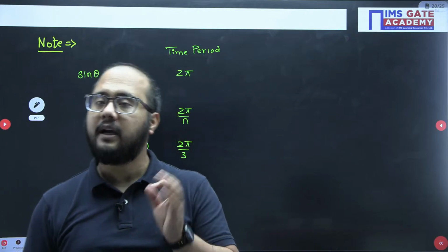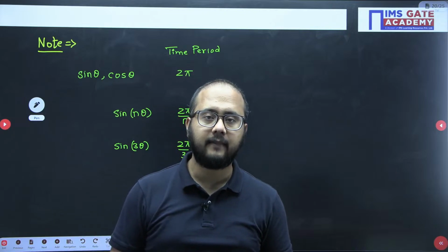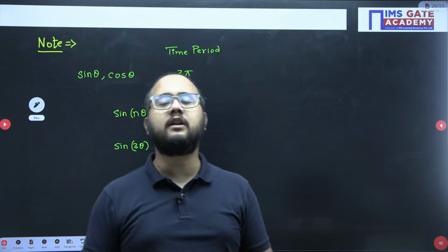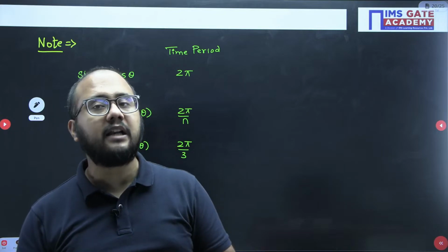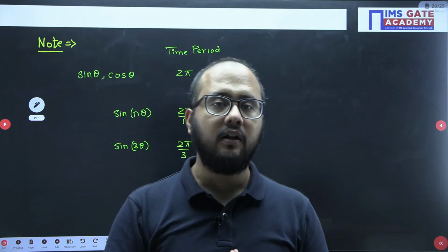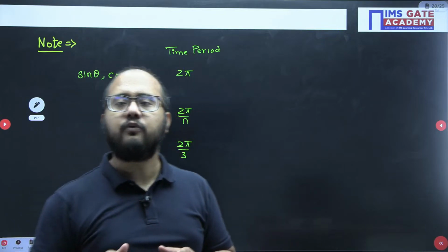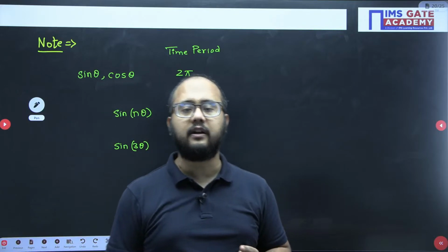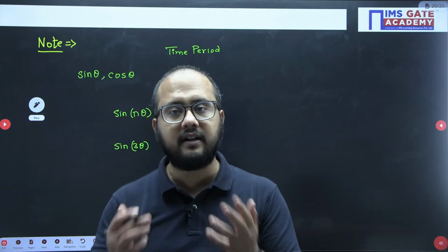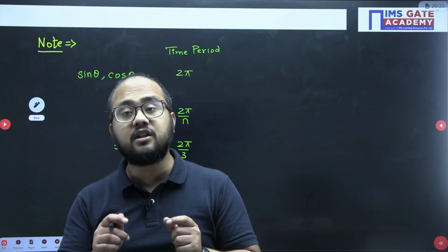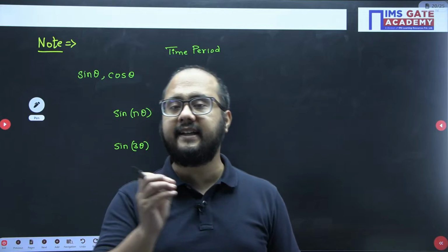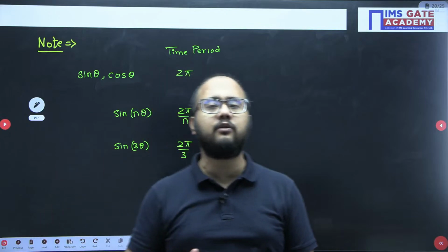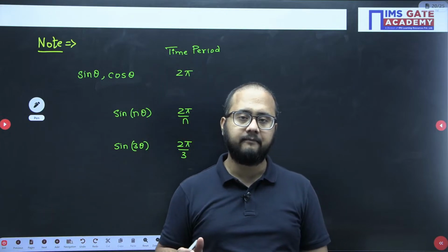Mean torque multiplied by omega average. So calculation of mean torque is very important, and for that, the work done per cycle is required. And as I already told you, work done per cycle calculation requires two relations. Either we can use the area under the T theta diagram, or the integration of the torque expression, T d theta, which gives the work done per cycle.